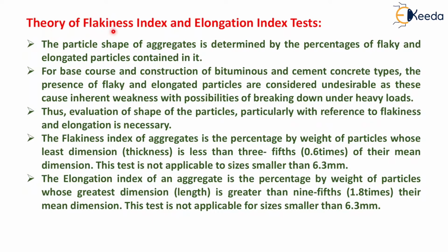Now, theory of flakiness index and elongation index test. The particle shape of aggregate is determined by the percentage of flaky and elongated particles contained in it. For base course and construction of bituminous and cement concrete types, the presence of flaky and elongated particles is considered undesirable as they cause inherent weakness with possibilities of breaking down under heavy loads. Thus, evaluation of shape of the particles, particularly with reference to flakiness and elongation, is necessary.